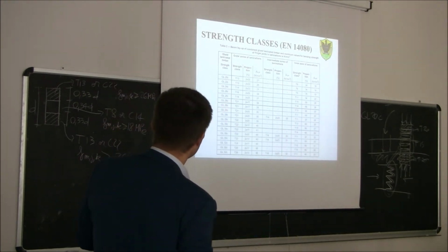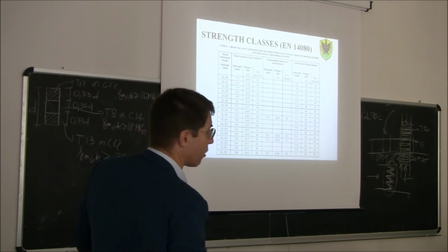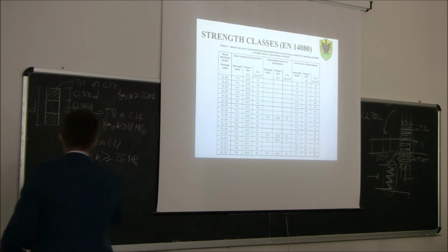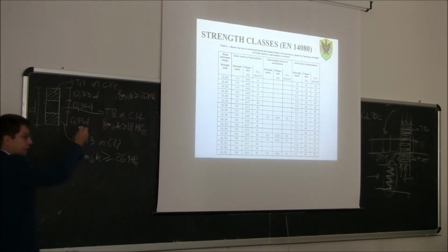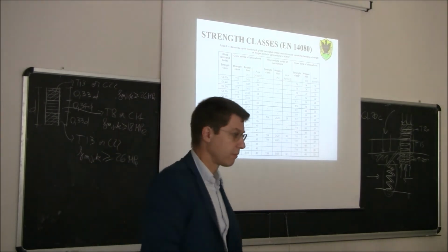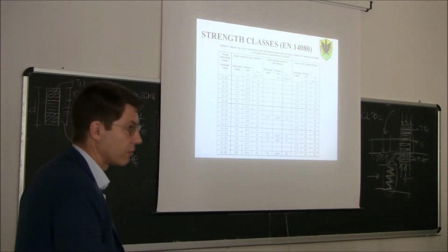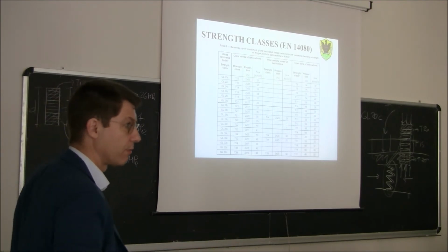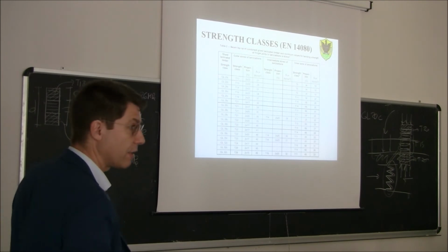Just a remark, you can see that for GL20C there is only one possibility. So we just need to use this configuration. Of course, then it depends on the size of the beam. Here there could be only 2 laminations, 2, or it could be more than 2, it could also be 4, 4 and 4. Okay? Or 3, 3 and 3. 1, 1 and 1 is not okay because it's too little. So we start from 2, 2 and 2, 3, 3 and 3, 4, 4 and 4 and so on, for this configuration here. Okay, it's clear?